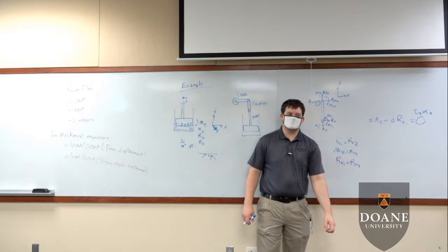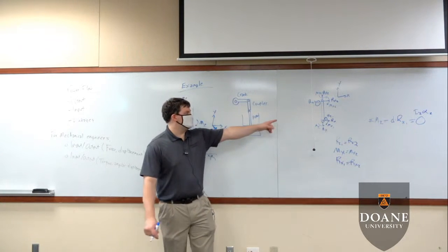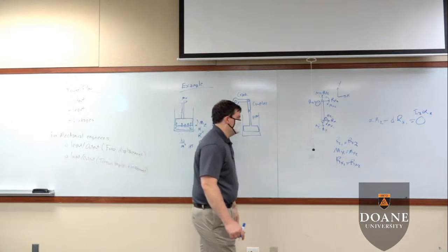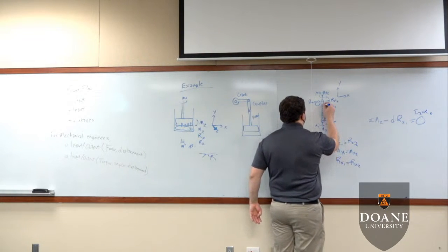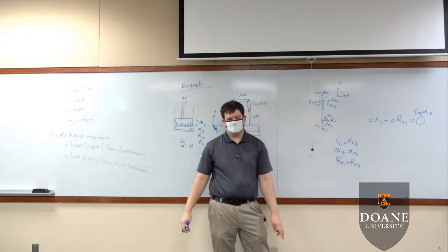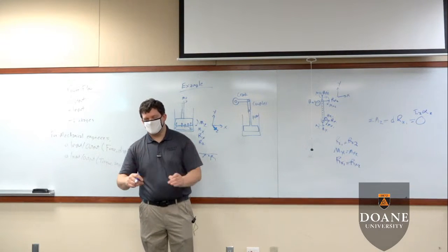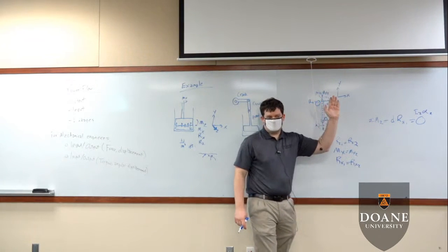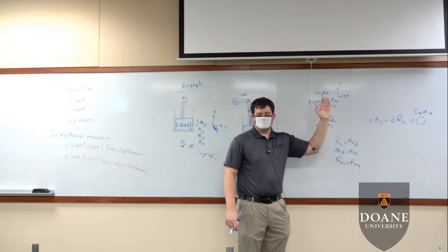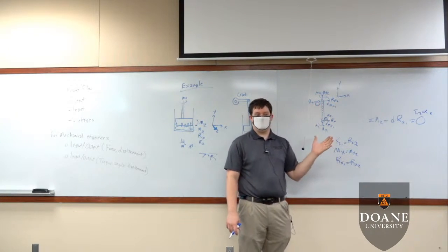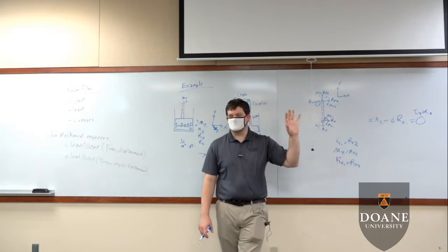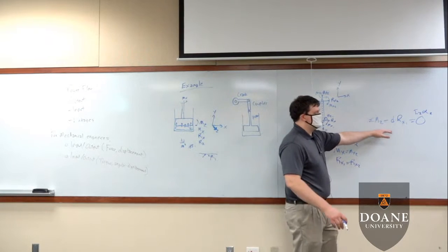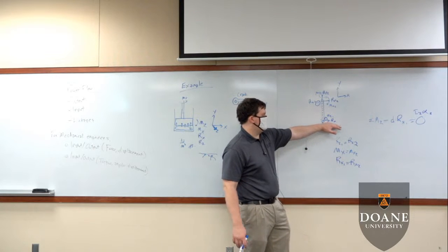We also know that Rx2 has to equal 0, which means because this component only has 2 revolute joints, it can only carry a force that is axial to that component. Which means the total net force transferred through this component will occur along its axis. Okay? I've said this before in this class, but this is the reason why. It's because if you calculate all the forces and all the possible forces it can generate, it is impossible to balance your z-directional moment if you have any Rx value.